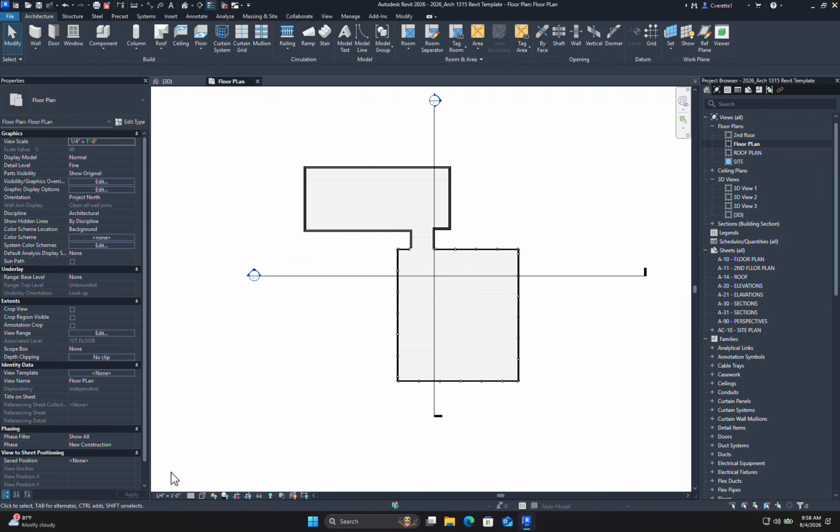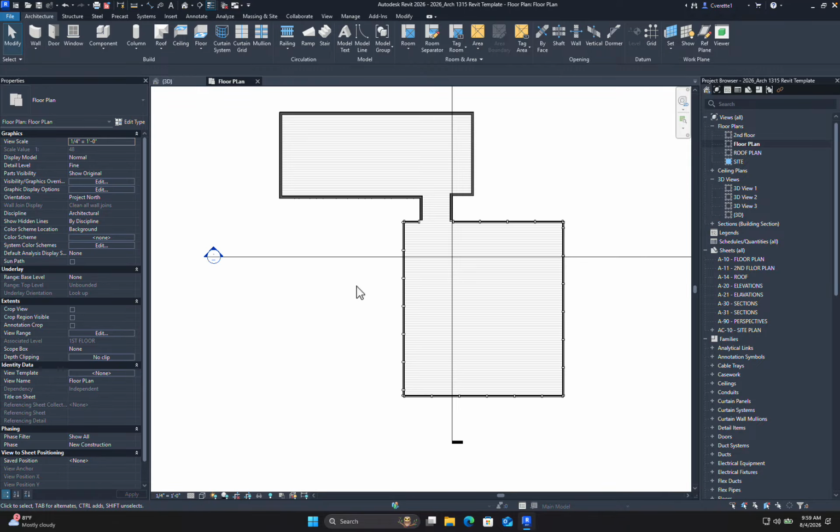In our case, I'm going to stick to 1/4 because that's a typical scale in terms of construction drawing. Keep in mind, usually the smallest size on the field is 36 by 24, whereas the largest size that we have on field is sometimes 48 by 5 feet, right? You can get a 4 by 5 foot drawing, and that's very typical of a skyscraper with multiple sets. The bigger the drawing, the more detail we can add in the scale. But in our case, it's adding that detail by making the detailed items smaller, right?